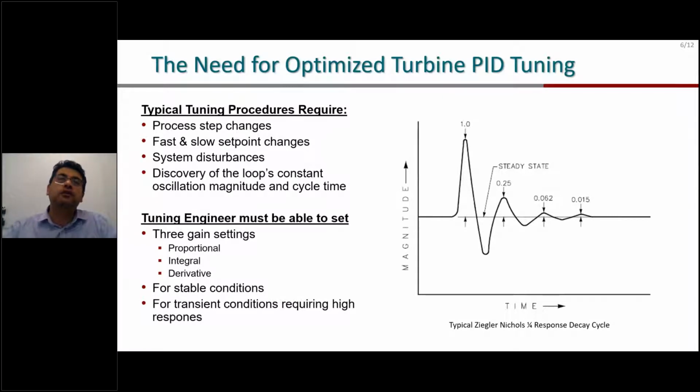You also have to understand the mechanical portion of the turbine, the actuator itself. What are the non-linearities? For example, poppet valves have non-linearity. All this is a criterion that you have to consider when you are tuning your turbine. You may have some non-linearity in the valve, so that you are at 20%, and then when you ask the turbine to open to 25, you get more response out of the turbine. That needs to be accommodated in your tuning so that you are able to accommodate these changes.